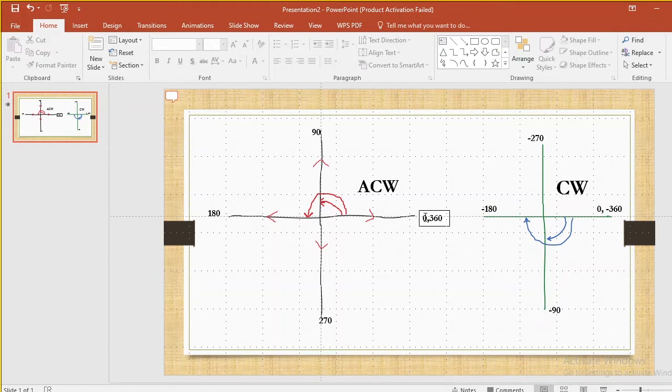Look at that, is what I have down here, which is saying that you are at 0 degree. Then you look at this movement. This movement is anti-clockwise. That is why I have this is anti-clockwise movement. So in AutoCAD, once you click that and move in this direction, you are 0 degree. Then when you move in an anti-clockwise direction, AutoCAD takes that as a positive angle. So that is why once we go in this way, this is 90 degree. Then you take this turn, this is 180. Then continuously you have 270, then back to 360.